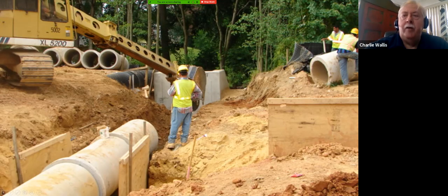This is a filter diaphragm being constructed. You will note that the filter diaphragm itself continues on this side, and it will go underneath of the spillway pipe and continue on this side. The concrete cradle has not yet been poured, but they've excavated down to earth, and it's ready to do the pour of the concrete cradle.